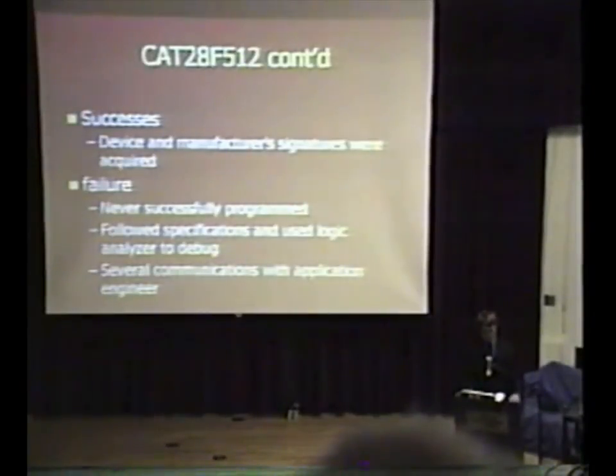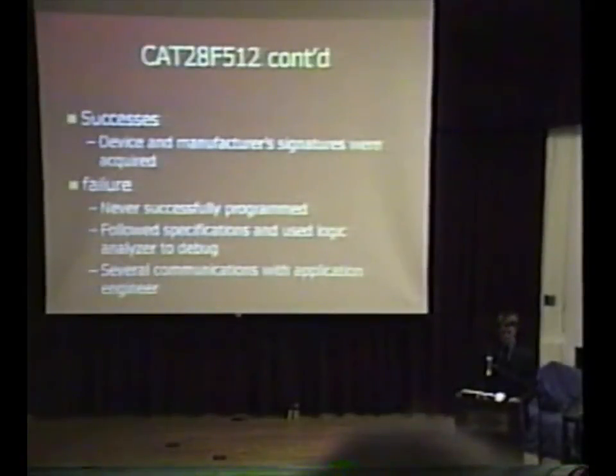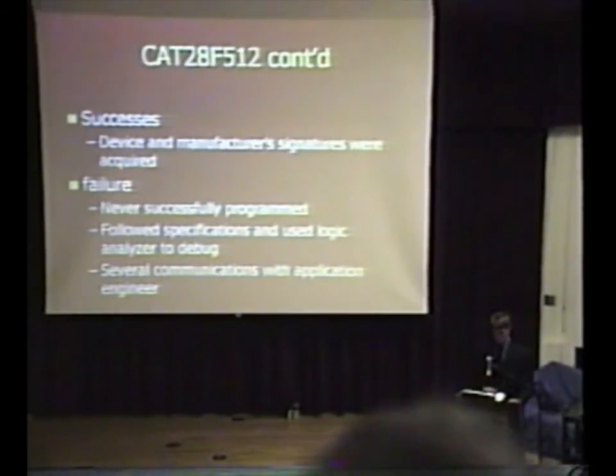The successes with the CAT were that I was able to get the device and manufacturer signature to show up. This means that the chip was wired correctly and was talking to me, basically. I was not successful in ever writing anything to the memory.